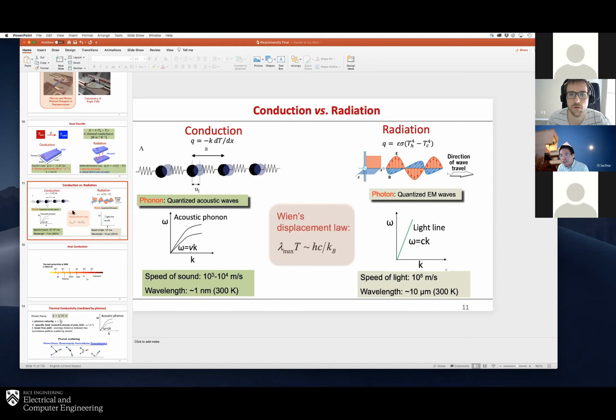If you have a crystalline material with a lot of defects, I guess when the defect concentration exceeds a certain level, you will probably also alter the phonon dispersion. But for most regimes where you study phonon scattering by defects, the defect concentration is usually very small, on the order of parts per million. That's what you have in doped silicon. The dopant concentration is very small, again on the order of parts per million. So in this case, the dispersion is usually considered unchanged.